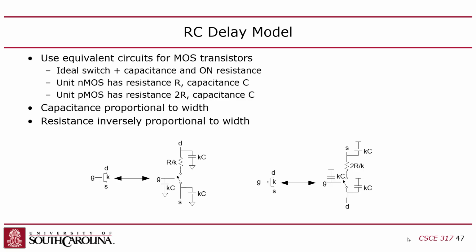Okay, and also the transistor itself, I mentioned this earlier, is a resistor, right? Why? Because, well, it's a semiconductor. So when the transistor is turned on, it still has resistance. There's still resistance across the channel. It's a small resistance, and it gets smaller the smaller the channel is, but it's still a resistor, right? So that's where your RC delay comes from. It's the resistance of the on transistor multiplied by the capacitance, right?